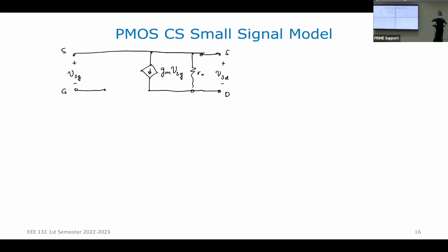I'm going to flip this so that S is below and then G and D are above. So if i-flip ko lang, dito ko lalagay yung S ko. Okay, and then here I will put G. So this voltage is plus minus VSG. But then, that is equivalent to plus minus VGS. Right? Kung dito plus minus VSG, pag ginawa kong positive yung taas, babalik na rin ko lang yung subscript. So this is now plus minus VGS.